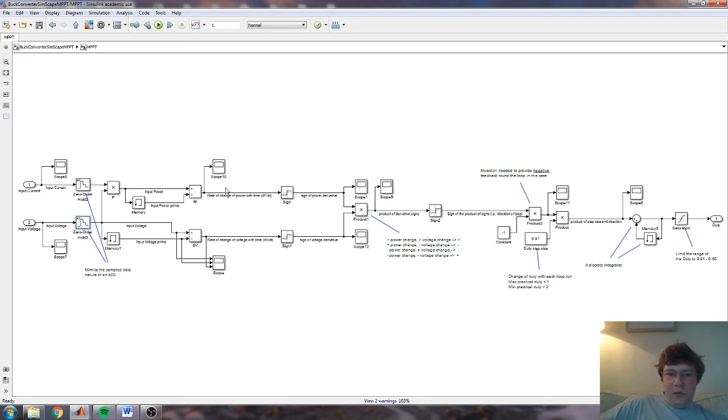We could at this point find power minima, and if we did, that would be troublesome because you could have your controller driving towards a power minimum, and the power minimum will be no duty, no power flow, nothing happening. Of course, that's not very desirable because you want the maximum power point. So we can look at the maximum voltage as well, because across the input we ought to find a maximum or a minimum voltage which is related to the maximum or minimum power.